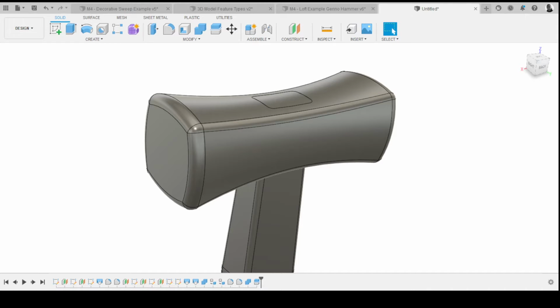But splitting bodies, and this, Charles, when you were asking me earlier on about splitting bodies ready for 3D printing stuff, you can literally just create an offset plane and split it with an offset plane. You can draw simply a sketch on a plane and use that sketch to drive a split. You can split things with any plane you can select that will cut it. And it's a really nice, quick way of just chopping things up.